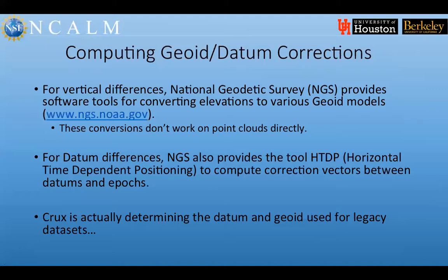Of course, the crux is actually determining the datum and geoid used for legacy data sets. So as an example, when Ramon and I were working on the El Mayor Cucapá earthquake, my Spanish was not so good, I couldn't read their notes, so I eventually convinced them to give me the raw data, and I just reprocessed all of the GPS to put it in a reference frame that I knew. Sometimes you have to actually call the state agency, and I know it's something a lot of people don't want to do, but you have to talk to the state surveyor, and he'll tell you what datum it might have been in. They talk a different language and what have you. But it takes a little bit of detective work.